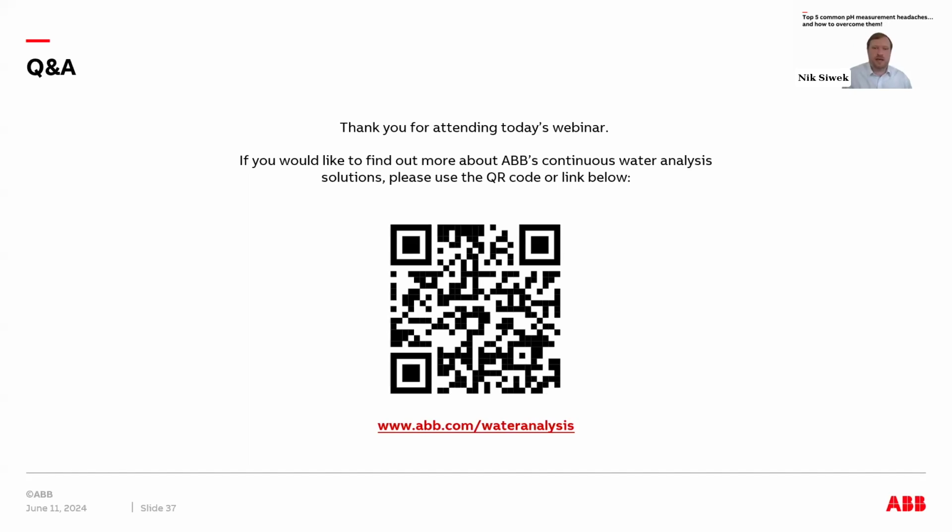So when you're looking at high purity, keep that in mind. You want something that is preferably a refillable design that keeps the sensor working longer and longer. Because at the end of the day, what's going to kill the sensor in high purities is not so much the glass dying, it's going to be the reference electrode dying quickly. So you want to make sure that you have the ability of topping off KCl salt within that electrode. That's going to be the most important.